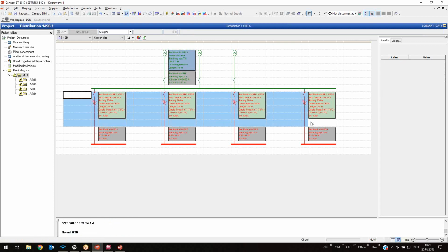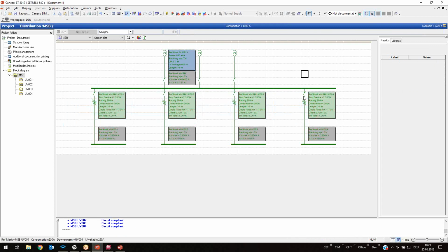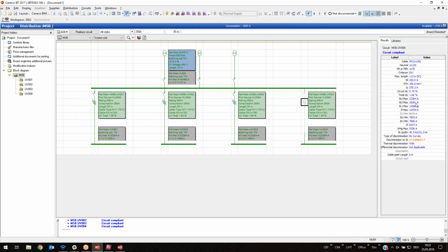So that means if I calculate these 4 boards here, the protection devices of these boards can handle all 3 trafos for the maximum short circuit current, and they also recognize the minimum short circuit current of 1 trafo for the tripping unit. So this protection device right now can handle all constellations of here. You see, 40 kiloampere in maximum and 7 in minimum.